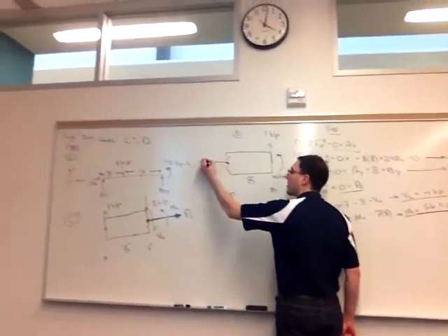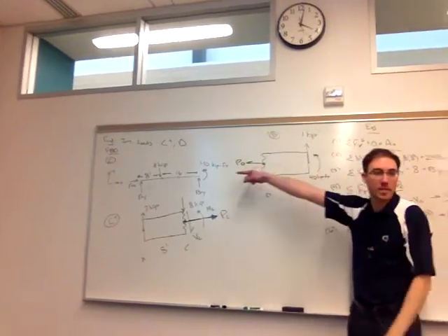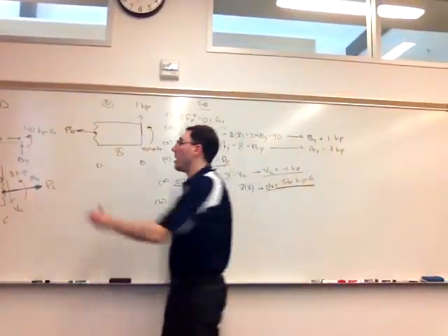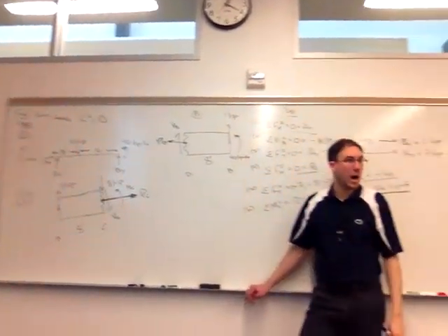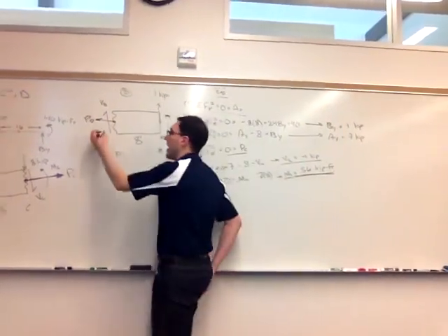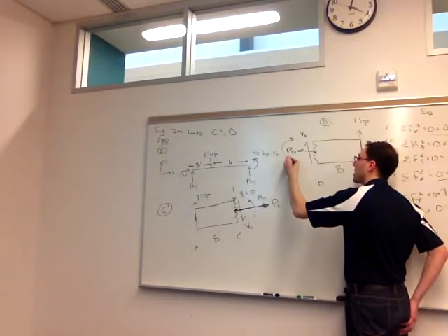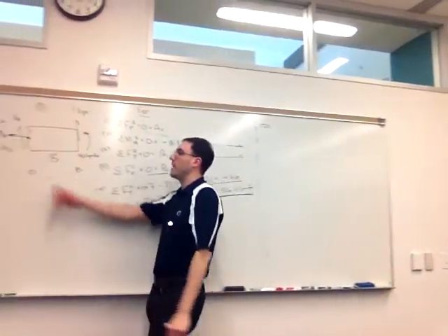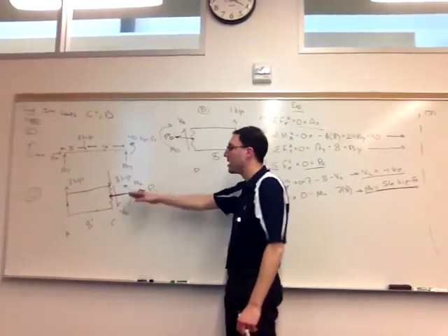And then at D, I'm going to have some internal normal force, P sub D. That has to be to the left because that's outward from the cut surface. I'll make the assumption that V sub D, the internal shear force, is up on this side. And I'm going to make the assumption that M_D, draw it here, is clockwise on this surface. In picture D, I have now introduced 3 different unknowns. Potentially, all 3 of these internal forces are different at D than they were at C.